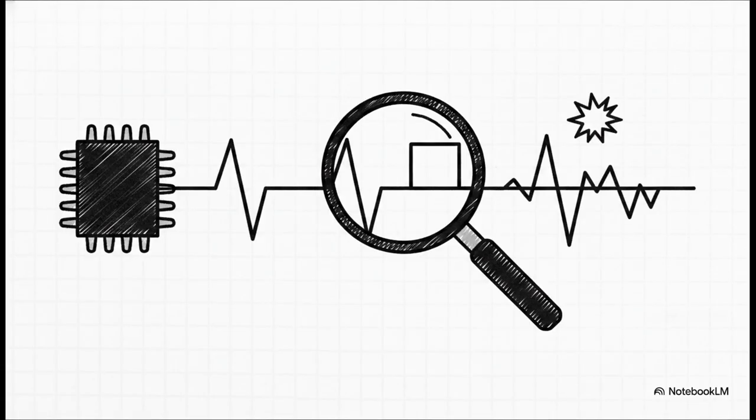But how do the chips actually know this is happening? Well, that's where the hardware check rules come in. In I2C, every single master must constantly sample the SDA, the serial data line, while it's transmitting. It's this continuous, real-time feedback loop. The master sends a bit out and immediately reads the physical wire to see if the voltage matches what it just tried to send. If a master outputs a 1, expecting the line to float high, but it reads a 0, it instantly knows another master is pulling the line down, and that mismatch means arbitration is instantly lost.